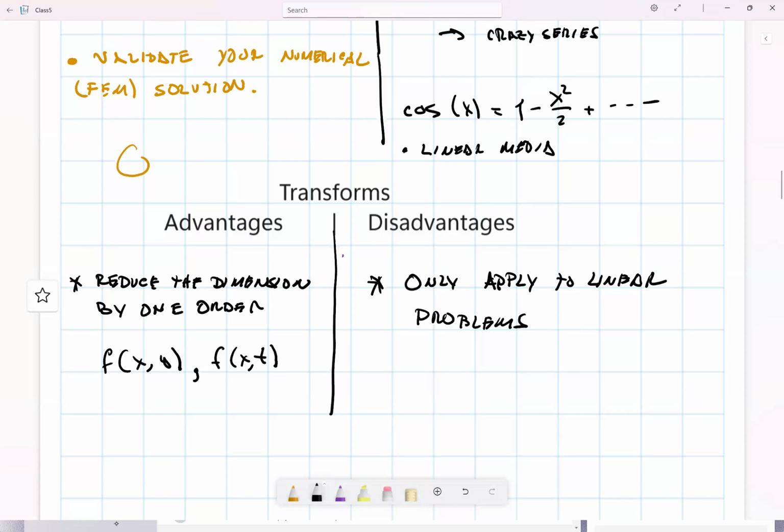I would put conformal mapping in the physical solutions column. Conformal mapping gives you, if you understand the physics, you could actually do it. Well, that's the way people did it. Before computers were powerful enough, I would say by the 1960s, 70s, many people were still doing conformal mapping because otherwise they couldn't solve the problem. And engineers of that time were very good at designing the shoes of the polar poles for synchronous generators. And they were doing all this with conformal mapping, which means pencil and eraser. Just the drawing.